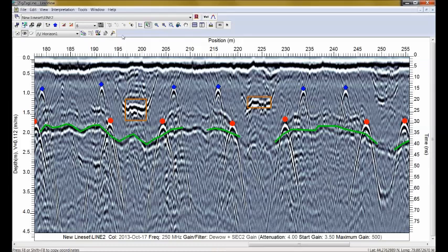Now I click on the glue bottle, and the glue bottle comes over. It turns red when it detects the end of a polyline, and then I can click and drag over and grab another point and then draw the line in between them. Okay, and that's the function of that particular button. When I'm all done, I can exit by clicking on that button again.